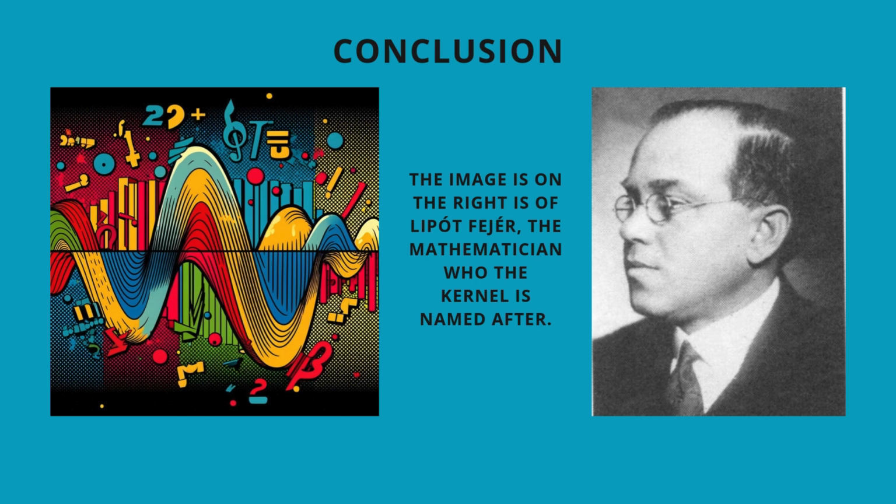You now have a working knowledge of the Gibbs phenomenon, what it is, why it appears, and how to address it. We started with a classic Fourier series approximation of a square wave, noted the persistent overshoot, and explored mathematical and practical techniques to reduce it, particularly Fejér summation. Keep this knowledge in mind as you progress in DSP. When you see undesired oscillations in your filtered signals or compressed images, remember that clever averaging kernels and summation techniques can help. With this, you've learned a valuable lesson in both the mathematics and the engineering of signal processing.